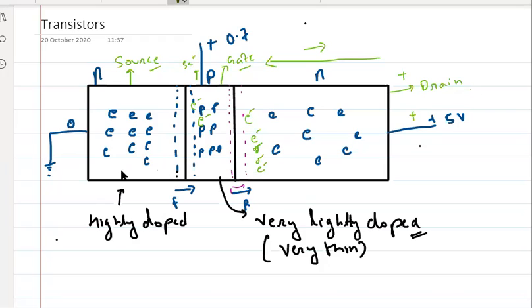Yes or no? Right? Now suppose we have 100 free electrons over here. Because of this forward biasing, 100 electrons will jump from here to here, so it will have 100 electrons here. Again, we have a potential difference now, so obviously these electrons will go outside. Now out of those 100 electrons, only 5 electrons will go outside. What about the 95 electrons? 95 electrons will find their way into this n junction. Yes or no?